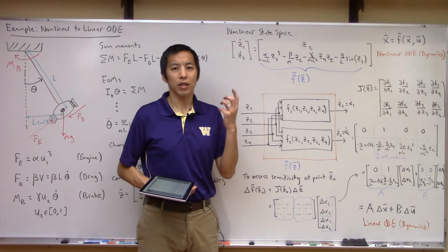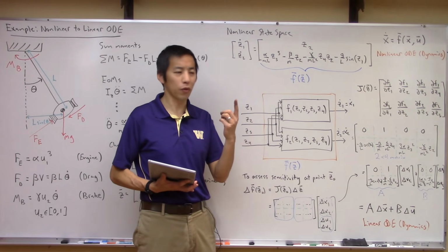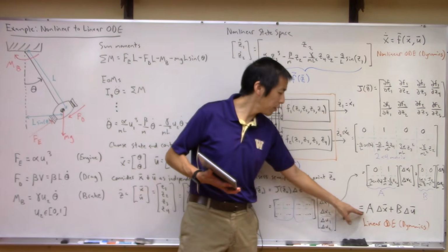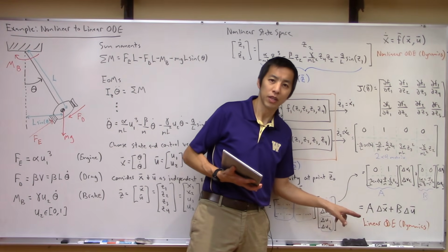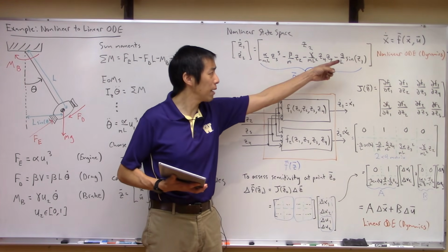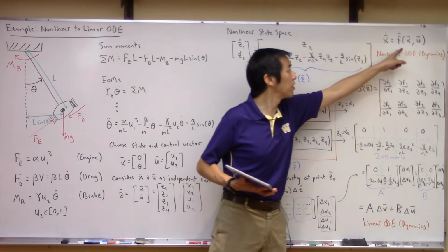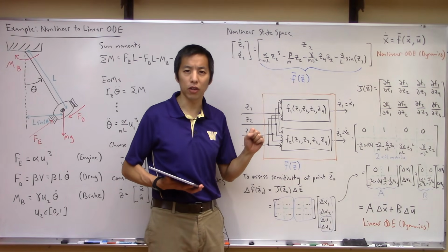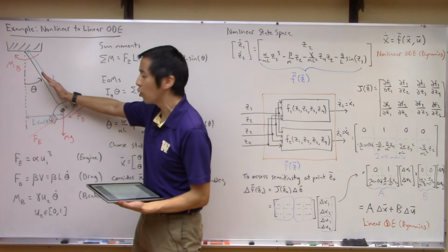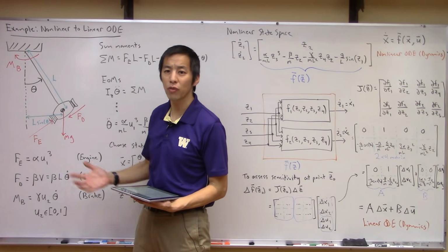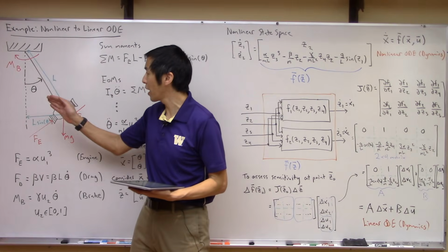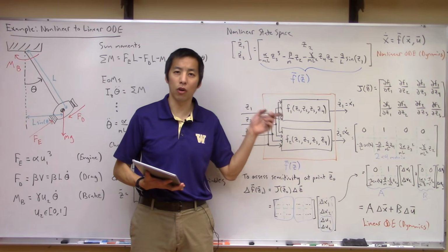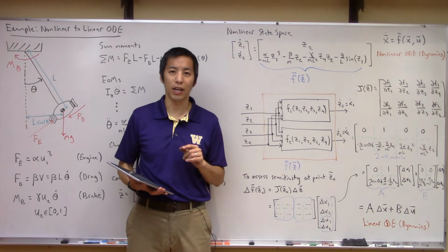And again, let's reiterate this to really drive the point home. All the Jacobian matrix is talking about, what the A and the B matrix capture here, is the sensitivity of the dynamics to perturbations in the state and control vector, depending on where you happen to be located and where you're operating in state and control space. So if this pendulum is canted over like this with a certain set of input conditions, its dynamics behave differently than if it were vertically straight up. And the Jacobian matrix captures all of that in a nice, graceful, elegant fashion.